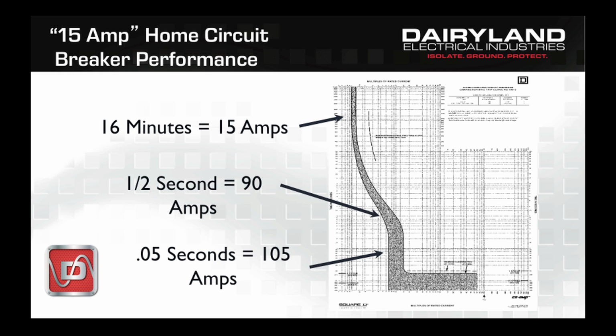If we look at this chart, we actually have time on the vertical axis and we have current on the bottom axis. As we move down the vertical axis to small amounts of time, it turns out that the circuit breaker will actually pass significantly more than 15 amps.